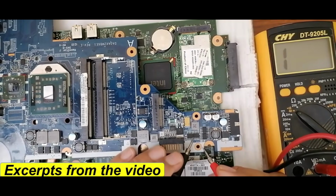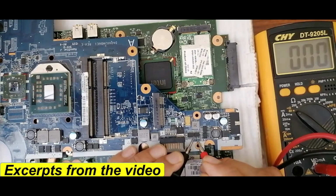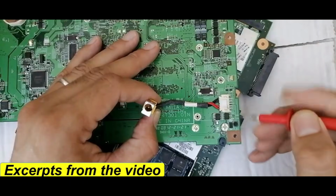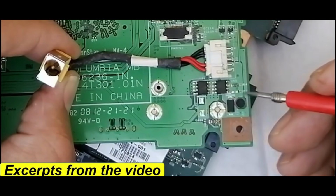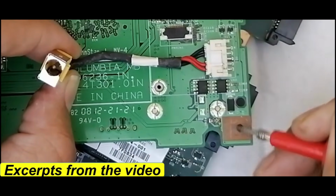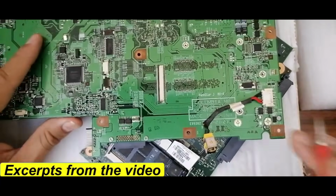So let's check on the motherboard. Let's put this probe on the first pin over here and check with this pin. We get continuity, a buzzer in the multimeter. The 3rd pin also has continuity, and the 4th pin too. So 4 pins are connected together. This is the cathode. As you can see, we have this white mark here, which means this is the cathode. This part should be connected to these terminals here, and this part should be connected to the ground because this is a protection diode. Let's use the multimeter and check this diode.